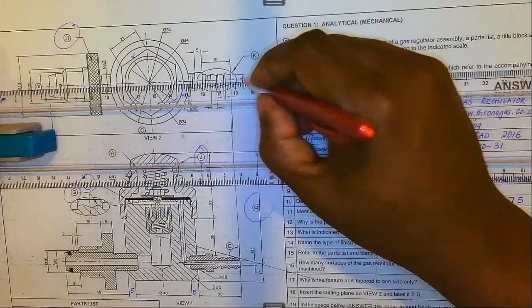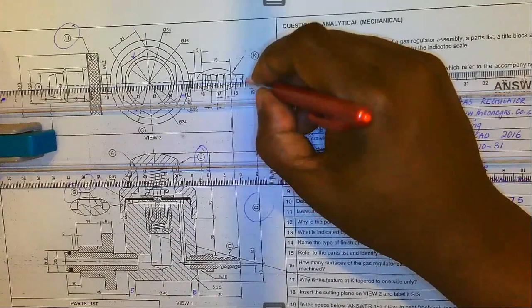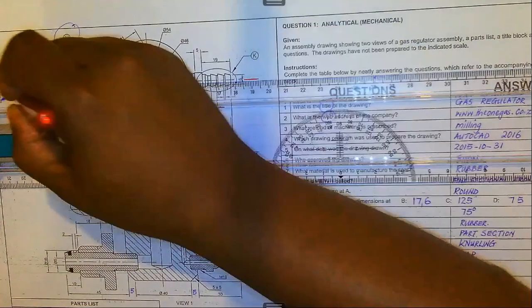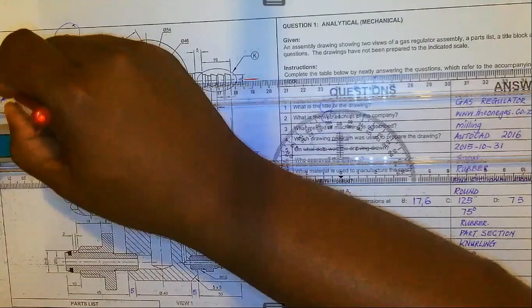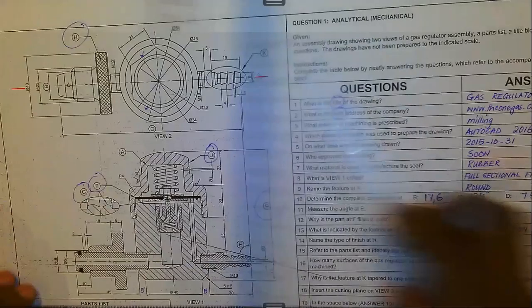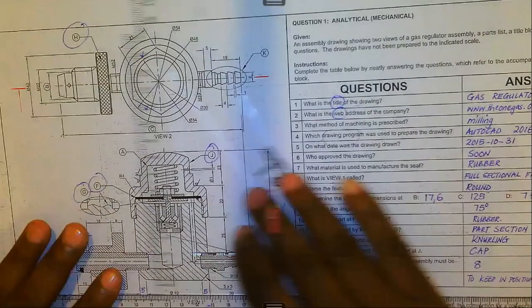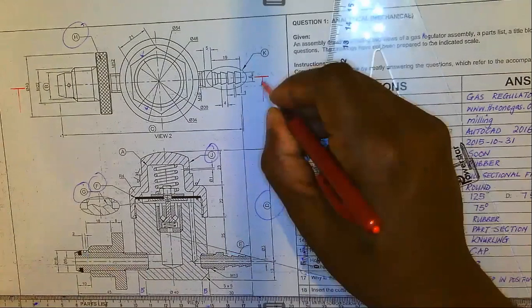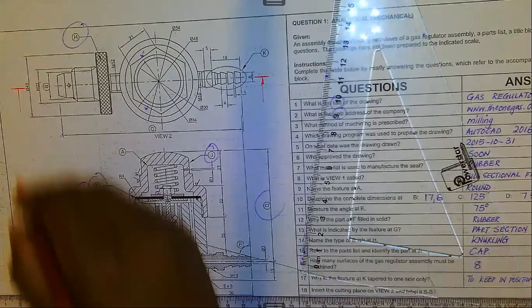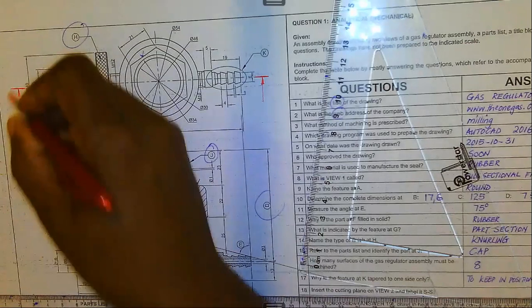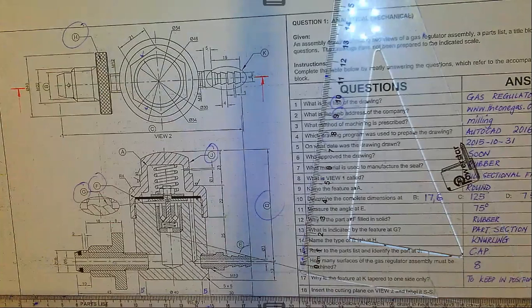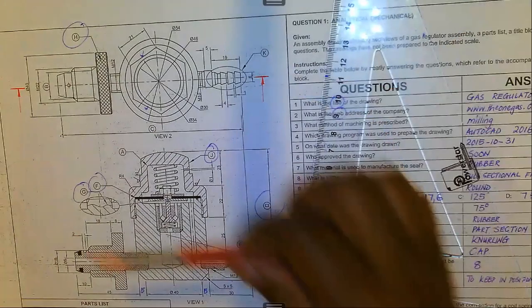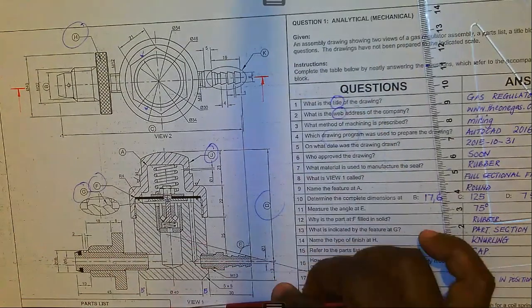So the first thing that we need to look at, we just use a different line, come here, thick end. Remember what I said? That's a thick end like that. Then we do this. If it's not so clear, we can show it by way of an arrowhead proper. Sometimes it would be enough for you to just thicken one end. So what it means, this is the position of cutting, which would result in us being able to see this section of front view, and that is the direction.